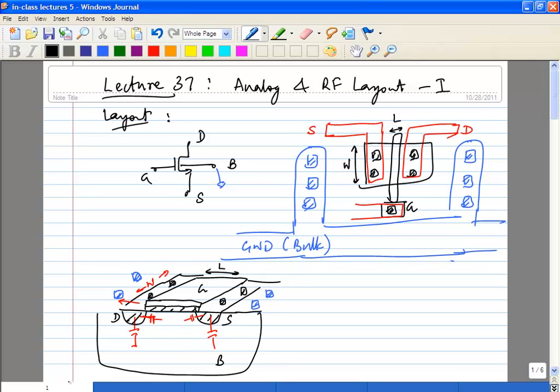The only thing you have to be careful about when you do all these things is parasitic capacitances. Typically these parasitic capacitances will be to the gate, or to adjacent lines, and these things may not be modeled very well. You have to be a little bit careful, even in your LPE step, the layout parasitic extraction step.